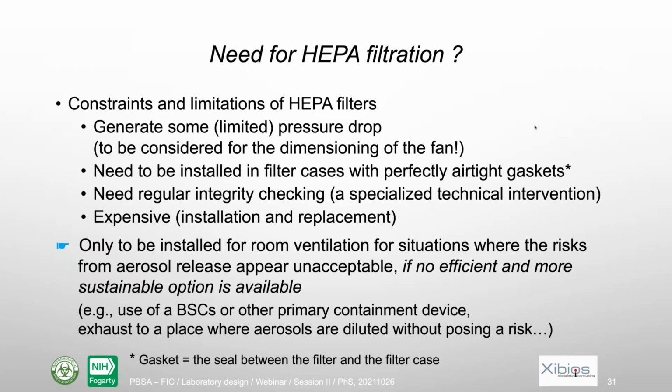Also, if you install HEPA filters, they need to be installed in filter cases, but these need to be perfectly airtight, including the joints around it. If not, since the filter offers some resistance, the air will go around the filter, and so we will not filter the air. Also, you need to check the integrity of the filter. You need to check that there is no leak either in the filter or in the gaskets. And that's a specialized technical intervention. You will need to have probably a contractor to do that.